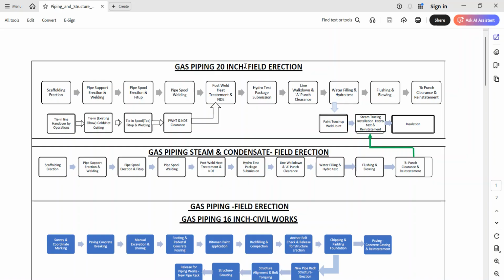Then once the water filling is done, it will be pressurized. We also have some inspection, checking whether all flanges are fine, and they will be raising the pressure slowly, so that if there is any leak we can check during that time. Before that, I forgot, for the flange bolting we also have a bolt torquing inspection report. They check the torque value and everything on the piping flange, whether the gaskets are used properly and the correct class has been used. Sometimes they also do the flange face inspections.